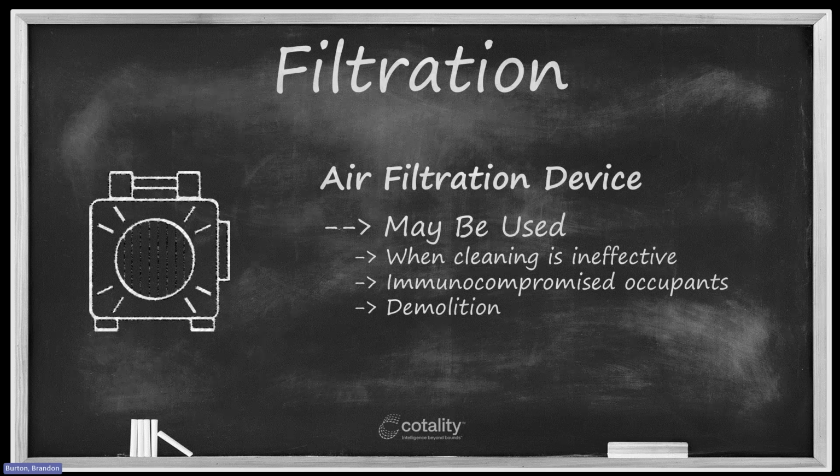The criteria that are given around air filtration is when cleaning alone is not determined to be effective at removing the soils and contaminants that are of concern, or when there are immune compromised individuals that occupy the space, or there is an active process of demolition that is occurring that is creating dirt and dust, and we're trying to control that. For any of these criteria, an air filtration device may be used, one or more. The only other criteria that is provided is when you are evacuating air from a cavity using an inter-air drying system, and that air has to be dumped back into the living space for whatever reason and not vented outside, then an air filtration device may be used there, or some sort of filtration system at the least.